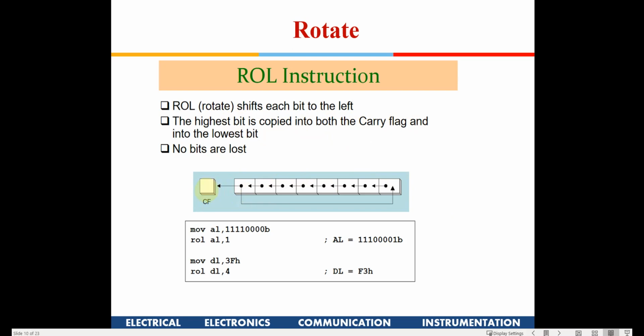Okay, so you have to be careful here. The carry flag doesn't get rotated here. It's not that whatever was in the carry comes back in. It is only within the register that the data is getting rotated. Each time, whatever is the MSB is going to come out here. Along with the carry, there is also a rotate, but that is a different instruction.